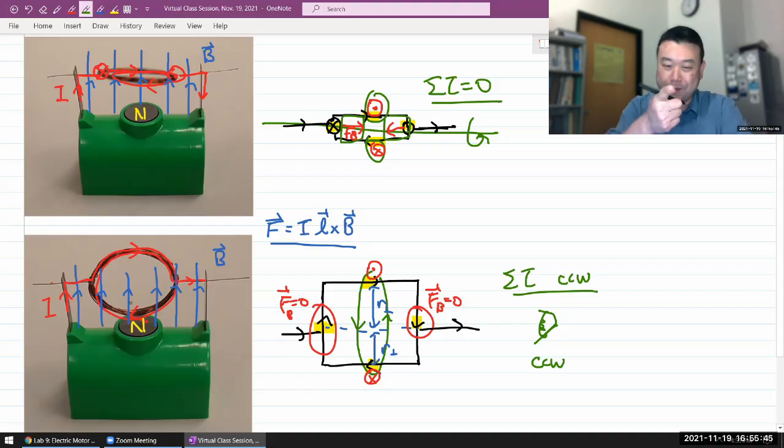Now, I don't remember in the demo if it actually spun in this direction or not. If it actually went the other way, what it would mean is one or the other: it could be that the current was actually flowing the other way. I don't know, I couldn't track the direction of wire in this screenshot. Or it could mean that the direction of the magnet is opposite. Flipping either of them will flip the direction with which the motor runs.